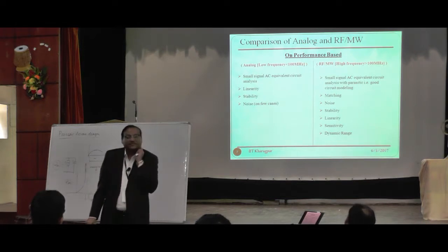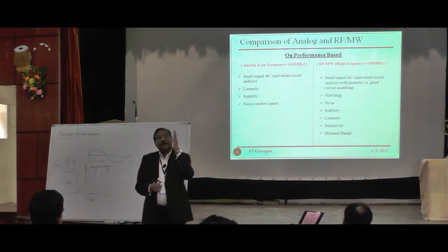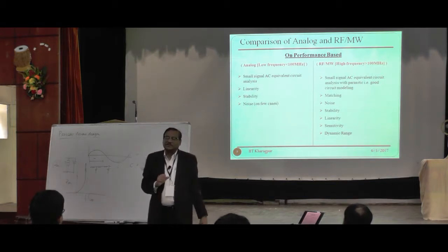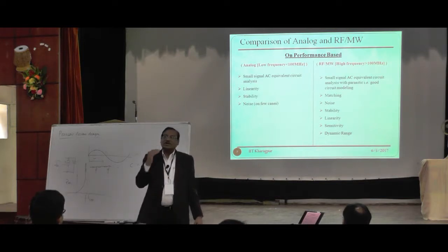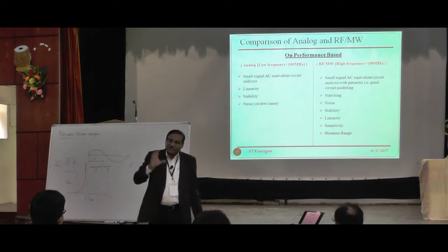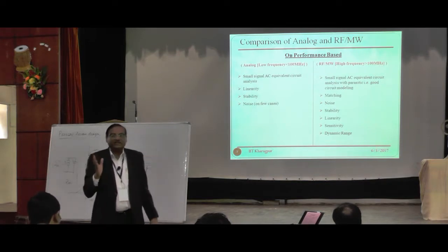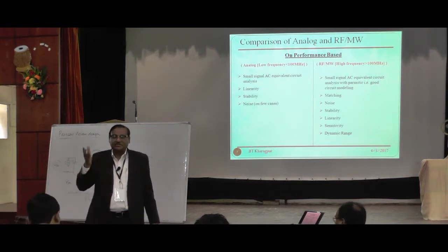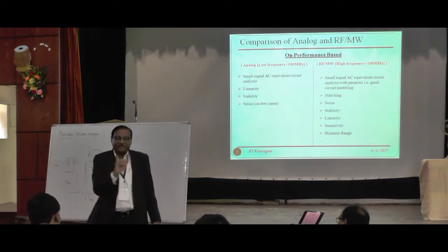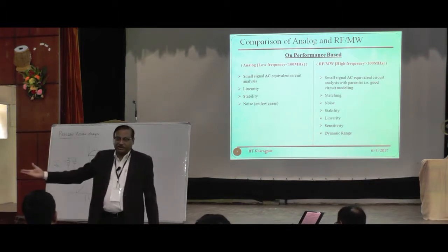Now what is that linearity? Linearity means that suppose I am feeding one signal, say 2.4 gigahertz. I would like to get 2.4 gigahertz at output. But how will you ensure? As long as the device behavior is linear. But all you know that any semiconductor is nonlinear in nature. IV characteristic itself is an exponential characteristic. And if it is exponential, I am giving an input periodic signal. You look at here, definitely it will give the nonlinear output.